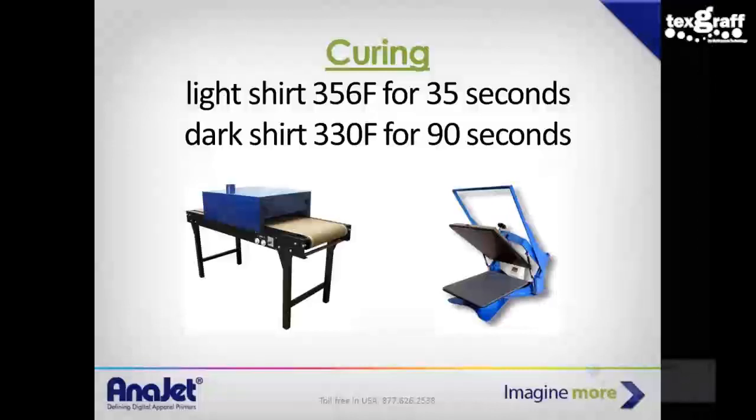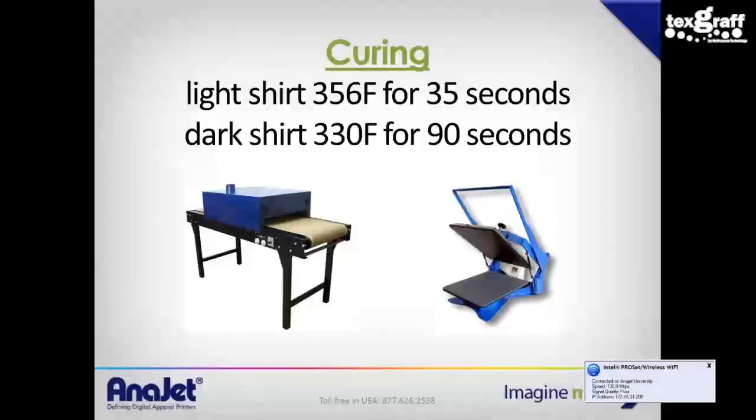Now, one last little note, that dark shirt setting, 330 degrees Fahrenheit for 90 seconds, will also work for light-colored garments as well. But typically light-colored garments print faster than dark-colored garments. So it's nice to have the option to be able to, say, print a shirt in 35 seconds and cure a shirt in 35 seconds so you can get a nice little production line going. That's the idea.